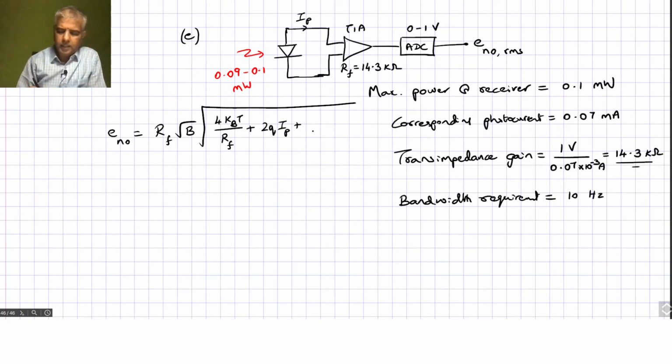And then you have a noise. So we are essentially capturing the noise current density, right? Then we have the noise current density corresponding to an op amp. So the variance is I_OA squared, plus E_OA squared divided by RF squared, because we are once again tracking the noise current density, right?